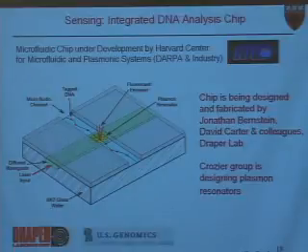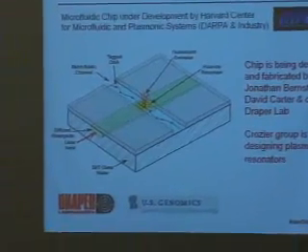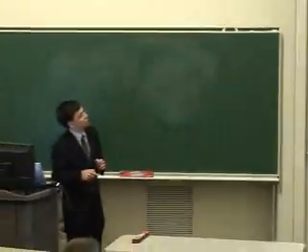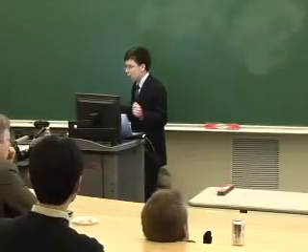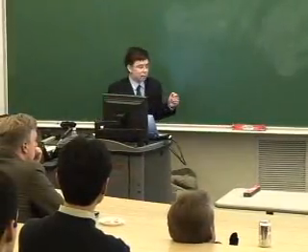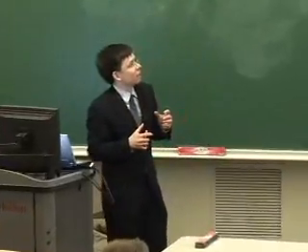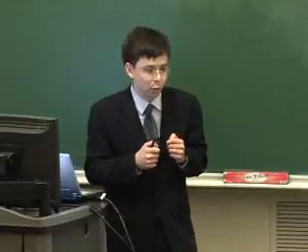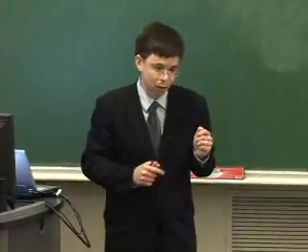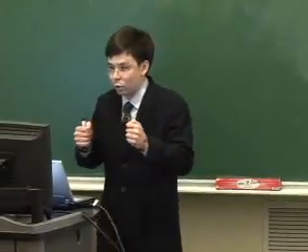Now, as you can imagine, one can't just put a single antenna structure or plasmon resonator into that channel, because the DNA is not necessarily going to pass near it. So instead, we need to span the width of the microfluidic channel with enough of these plasmon resonators. But what happens when you do that is the plasmon resonances, the fields couple together. And that can lead to a significant modification in the plasmon resonant frequency, the frequency at which, if we illuminated that with light of that frequency, we can excite a very strongly enhanced fields around these particles.